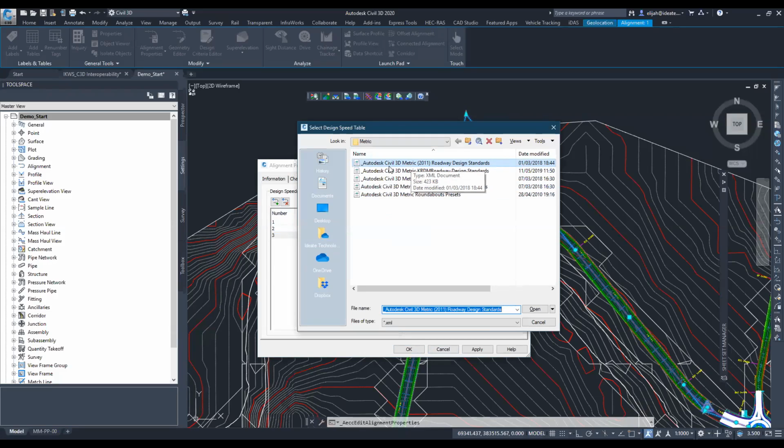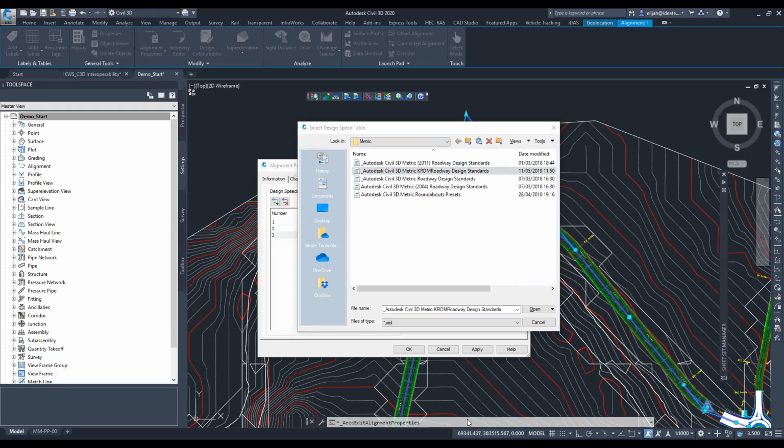So you can see, right now I'm still using AASHTO, but as I said, you can customize each of these design standards to meet your local condition. Like the one here I'm having, which you have customized for our local condition here, that's the Kenya Road Design Manual. And it's the same one which I've opened here. So you just need to open it as a text file, and you can now start defining each of those parameters in terms of maybe the minimum radius, speed for each of the curve radius, the grades in, the grades out, and the K values.